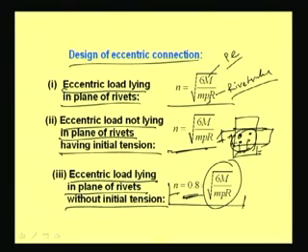Approximate means M is approximate, P is approximate, whether P has to increase or decrease, what the total length and depth will be, all those things have to be decided finally. So, after deciding we have to check once again to see whether it is okay or not, right. And what I told is that when it has initial tension, when the rivet is hot, and when the rivet is cold, initial tension can be neglected.